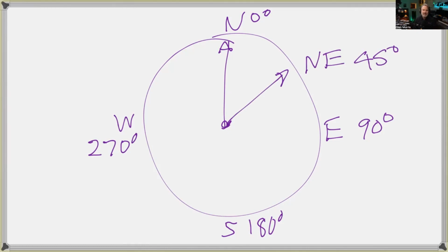South is 0 degrees. I got caught out by this when I first started using solar tools. It was a German tool, and it defaulted to equator facing as south, and I couldn't work out why my designs were so terrible. Fortunately, I never installed them. I just couldn't work the numbers. How come winter's the best month and summer's the worst?